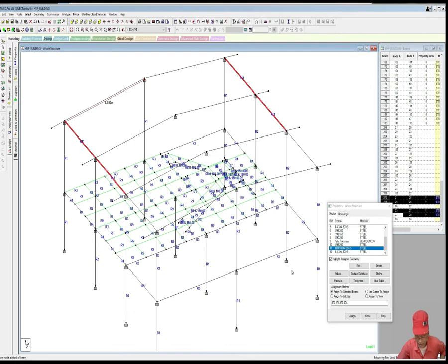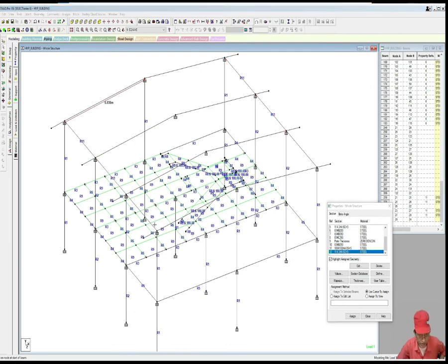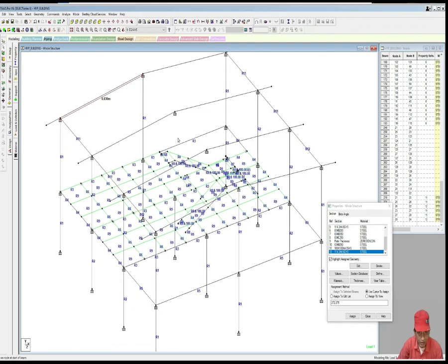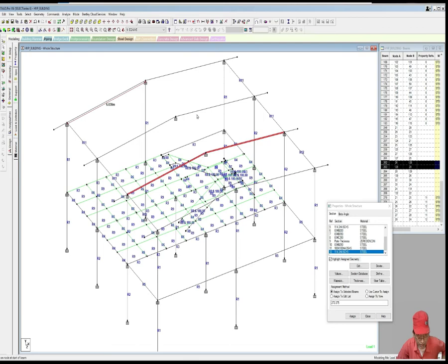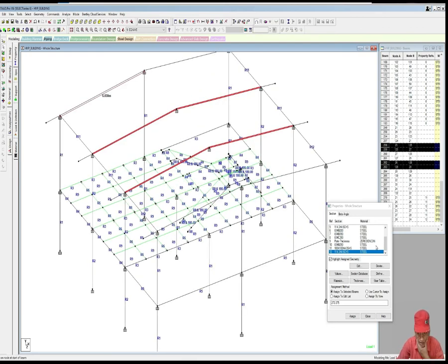Now select this strut and this strut. Okay, this is 100 mm nominal medium size pipe, and these are tube sections. Now see, these are 11, 12 meter spans, so we need to have a good depth for the rafter, something similar to the size of the column we had taken earlier.